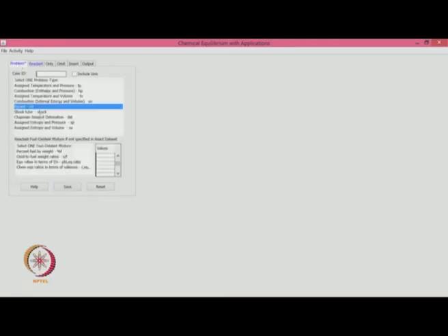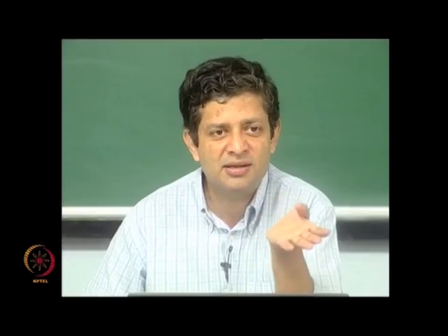HTPB will have an OH radical at the end of the chain. Even if we neglect it, it does not matter as much to what we are doing. So, for a solid propellant, not everything is preset. In some sense you just have to define what the percentages are, and that should automatically take care.